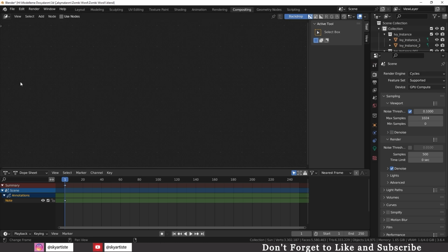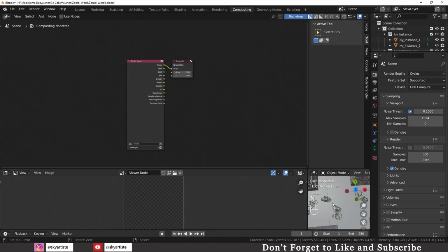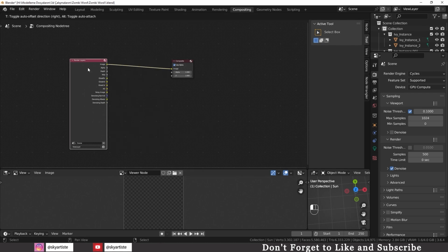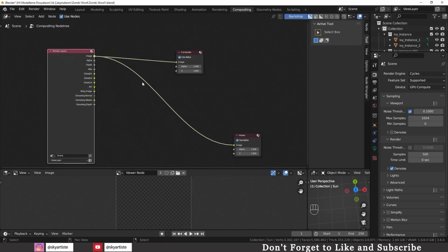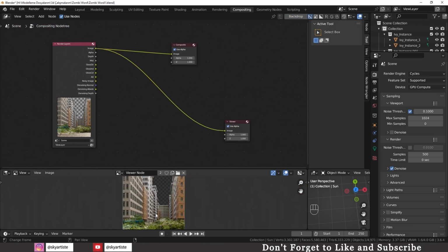We need to move to the compositing panel from the top and get the other channels. By rearranging the windows a little, you can see the buttons in the lower right corner again. Even though I added the viewer, the render does not appear in the background. I select Use Nodes above and it still does not appear. It starts to appear when you press the backdrop button on the top right.